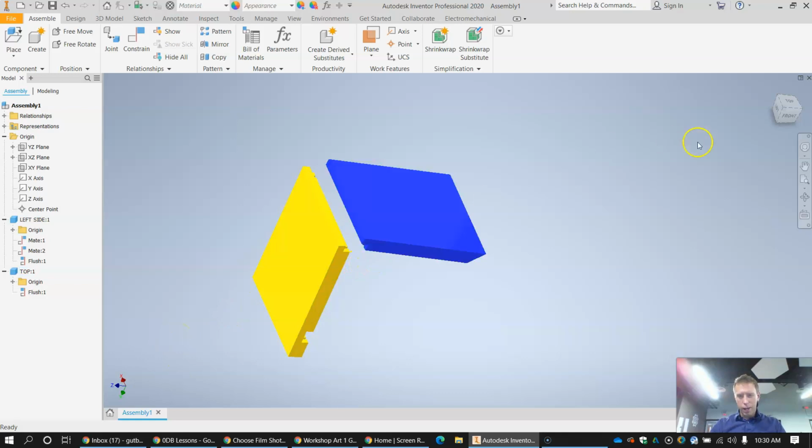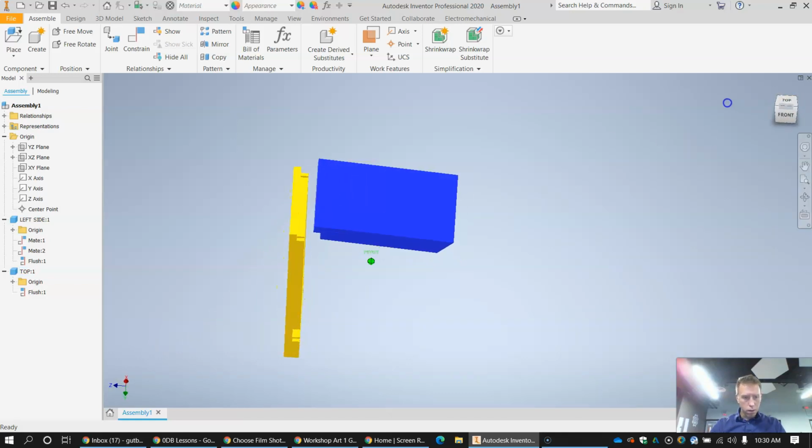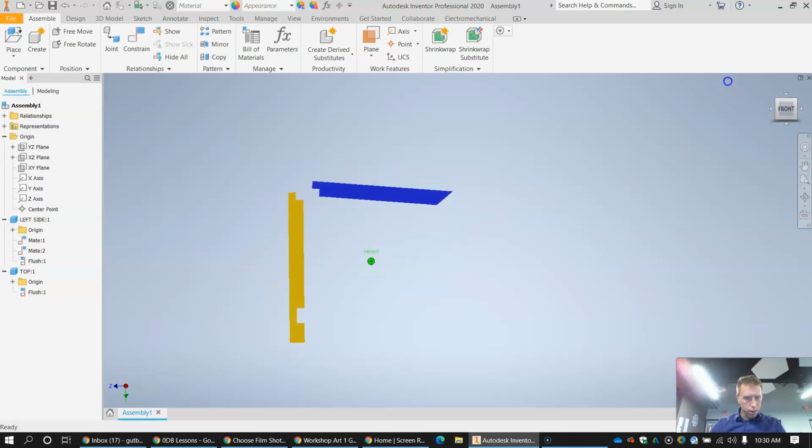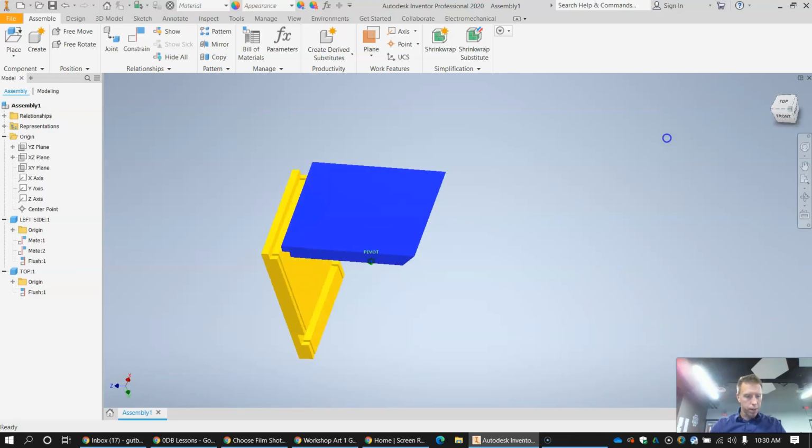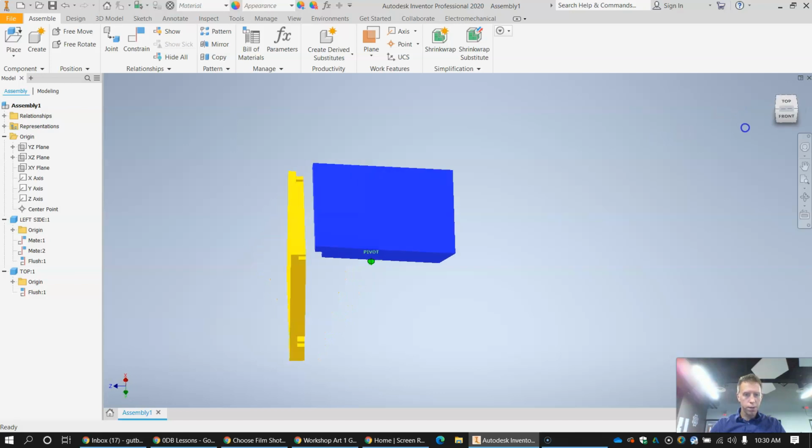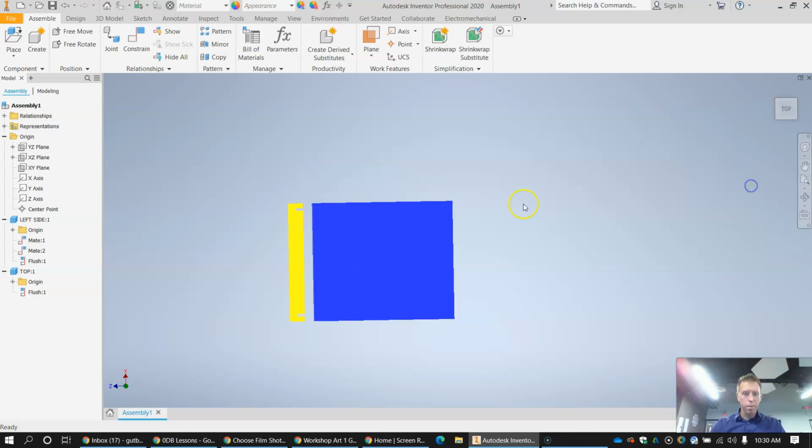The constraint that I did looks like it's the z-axis. I'm sorry, I messed up there. That's the x. Right now in this instance, I stopped the x-axis. Like these 2 surfaces are in line, I can't move them this way from each other. So I did the x-axis. You can see it there. The arrow points to the surface that I did.